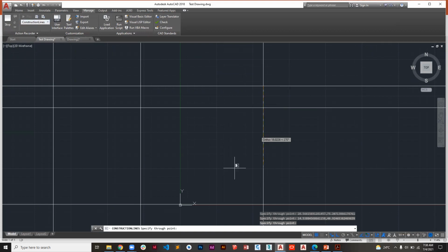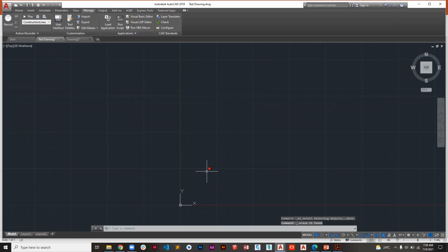Yes. Yeah. So that's how you can use action recorder, but it can record a very big portion, like you're doing a certain drawing and you record it. So maybe that can work better than blocks. I don't know, it just depends, but you may find that blocks work better. I think blocks work better because blocks you can edit them.